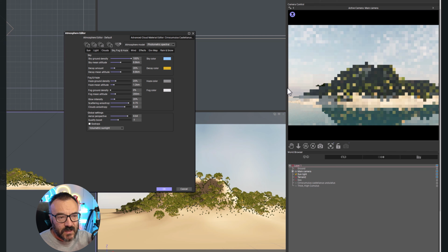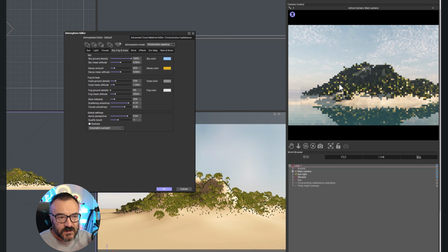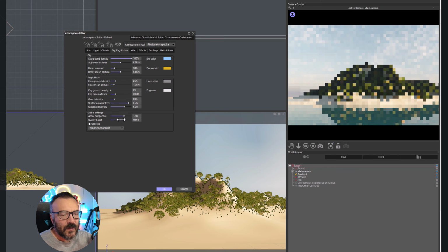And you can see as we added aerial perspective, it did create slightly more, which is good. Maybe a little bit too much. Yes, let's reduce. I also like to use the quality boost. By default, it is a minus. You want to put at least 0 because of quality, otherwise you will have grain in your render. I think we'll keep the rest about similar here.